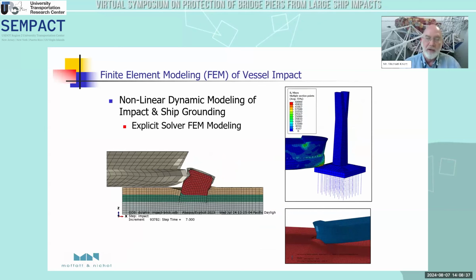We use similar modeling to look at protection systems. To the left here is a large diameter dolphin being impacted by a vessel, and we're looking at the deformation of that dolphin, its ability to absorb the ship energy before the ship makes contact with a bridge pier.